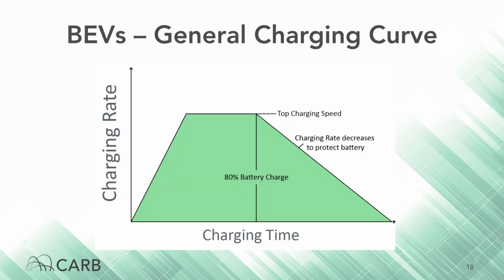So I mentioned something called the battery charging curve, where I explained that EV batteries don't charge at constant rates for the entire charge duration. The on-screen depiction of this charging curve illustrates a basic and general depiction of this fact. You'll notice that the charging rate, depicted by the vertical axis on the left, caps out early in the charge time and then decreases drastically after 80%.